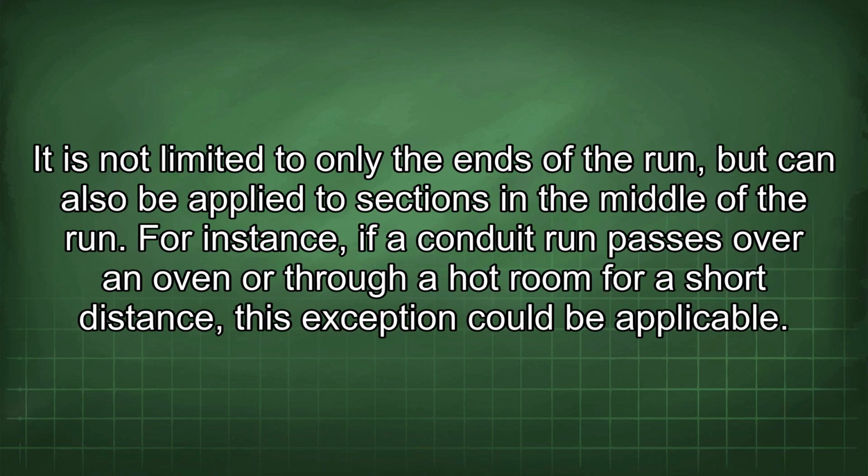It is not limited to only the ends of the run, but can also be applied to sections in the middle of the run. For instance, if a conduit run passes over an oven or through a hot room for a short distance, this exception could be applicable.